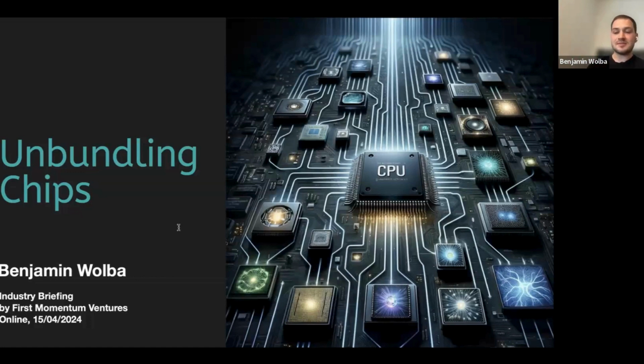And there are a couple of cool startups. One example is Corintis. They map out the heat distribution of a given chip, and then they design a cooling system specifically for that chip. And you get these very cool looking fractal structures that really account for the heat distribution of that very chip. It's cool. And maybe one last thing on that, people are looking into diamonds for chip cooling, because diamonds have one of the largest heat conductivities.